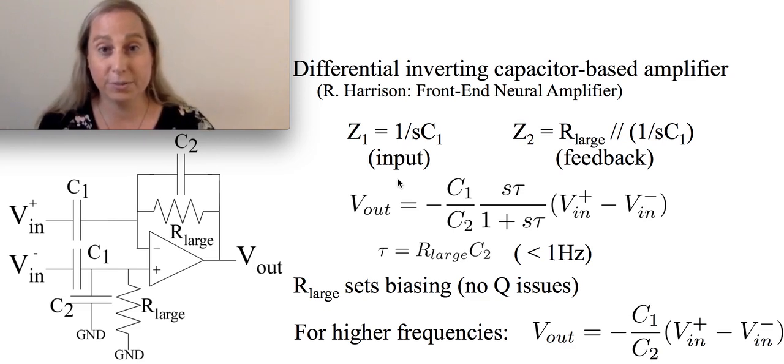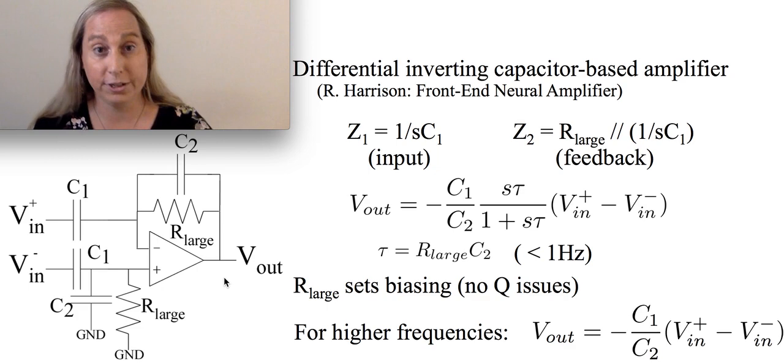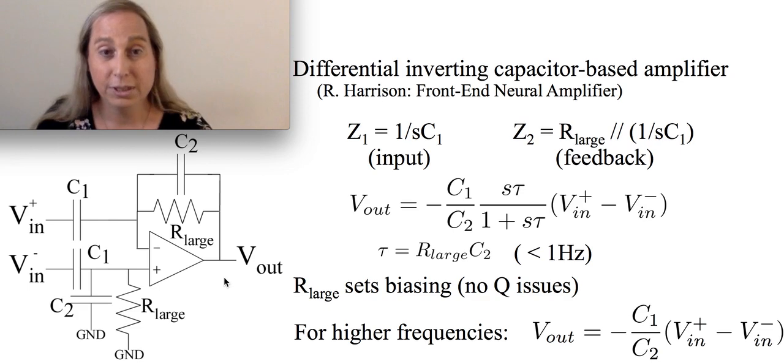But I want to talk about this in terms of a practical example that you see used particularly a lot in the last, say, decade or so in terms of looking at really small voltages, particularly in a neural amplifier or neural front end or other kinds of very, very small signals, where I'd want to be able to take a differential input and look at the output voltage. But I want to be able to do this entire circuit, say, on an integrated circuit. Because in integrated circuits, typically capacitors are easy to find. Resistors are actually hard to do, except for some interesting device level properties. This is quite common in terms of neural amplifiers.